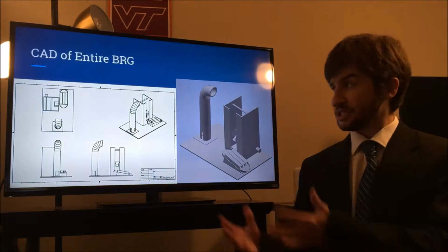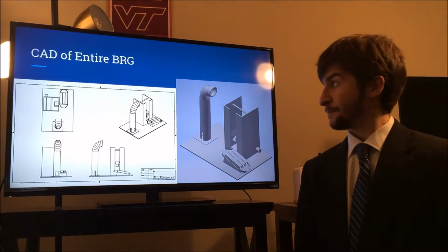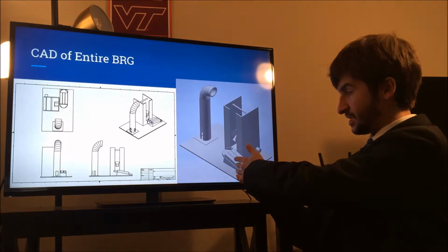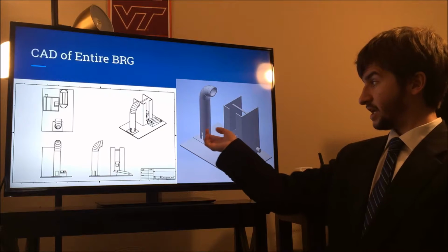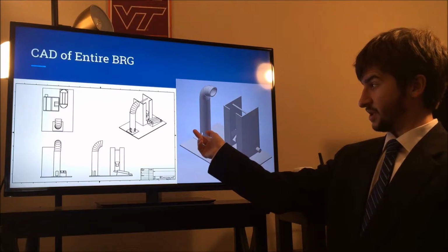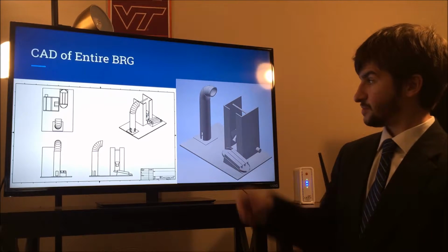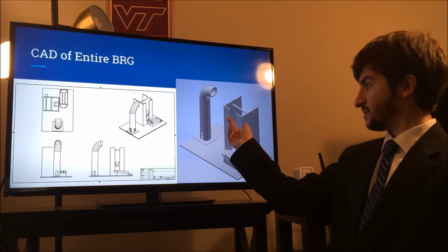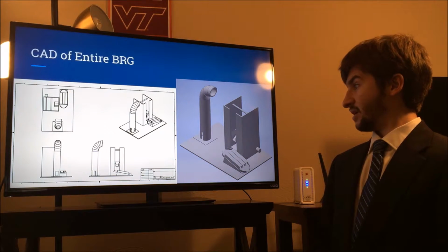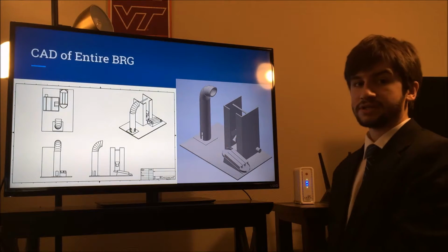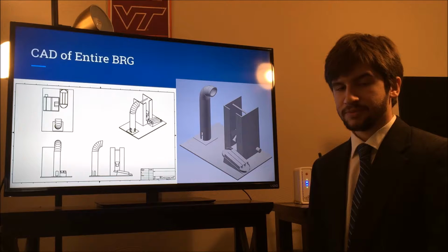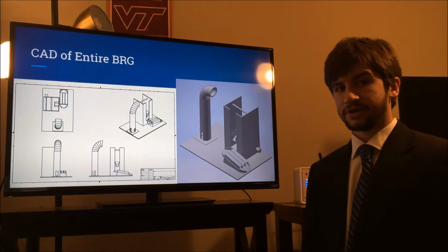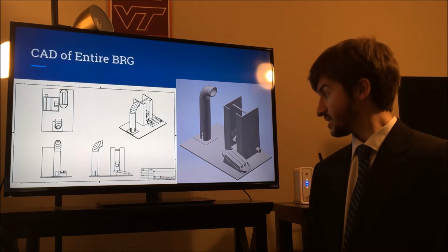spring cannon. This is our 3D CAD model of our design. We have the spring cannon, the kinematic elevator, and the velocity tunnels. The ball enters the spring cannon first from an entrance ramp. The user pulls down the spring, which will launch the ball at the proper velocity into the elevator, which then, if that's at the right height, it will roll successfully into the velocity tunnels. From there, the user selects which tunnel the ball rolls through, and from there, if they get it correct, then the ball proceeds to the exit.